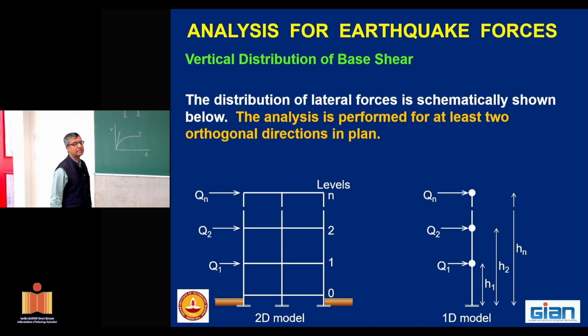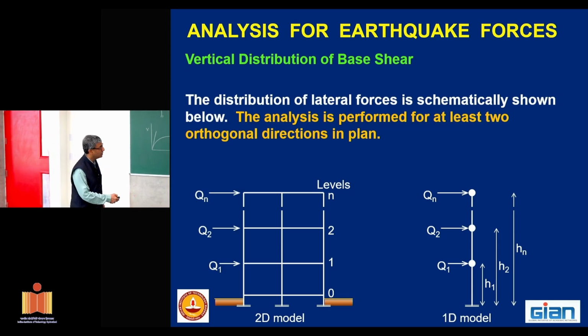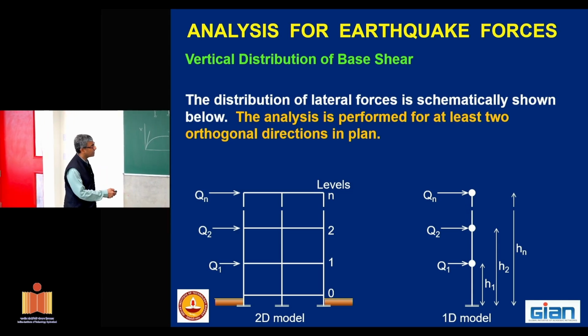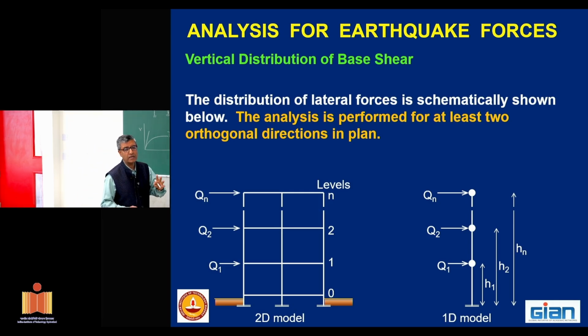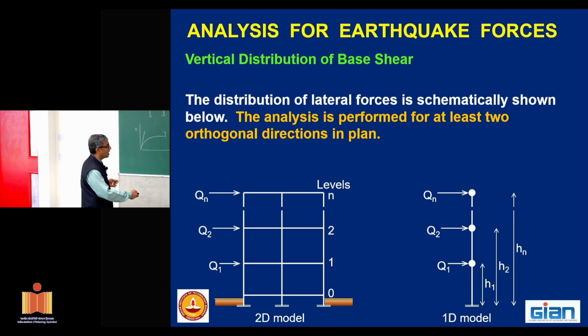Coming back again to the stick model, what are we going to learn at the end of the class today when we do the tutorial? Today we are going to learn how to compute these lateral forces with which I will be doing the structural analysis. That means first I need to get the seismic zone map, estimate a time period, get the Sa by g value, consider some values of I and R, and I can compute the base shear. Once I have computed the base shear, I have an expression to distribute the base shear along the height.